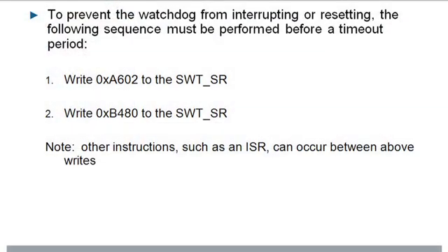inputs and outputs. And there will be a number of channels, dozens of channels. Each channel has a pin, and you can specify, are you a PWM? Are you an input capture? Are you a one-shot output, etc.? So we're going to go through that, and then we've got another exercise.